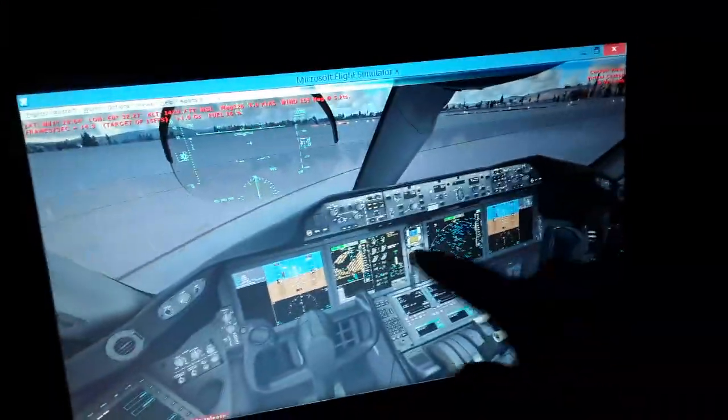You can see here the navigation display. You can see the airports, as I told you. Also, we have the nav aids displayed, the navigation aids, the workstation, the ADFs, the NDBs. Also the waypoints, which are horizontal and vertical navigation fixes. Those we have to cross through. We're gonna select some using the flight management computer and gonna cross them during the flight.